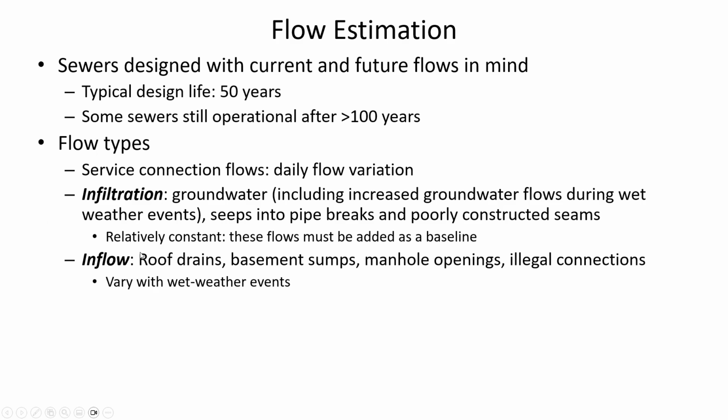And then inflow are flows that are coming into sewer pipes that aren't necessarily the main wastewater constituent that people are generating. So if you have a pump in your basement to make sure that water doesn't get into your basement, like a foundation drain, and you're pumping it to the sewer, that would count as inflow. Or openings in the manhole, like the little vents that they have in manholes, sometimes rainwater can get in there, and that contributes to inflow.